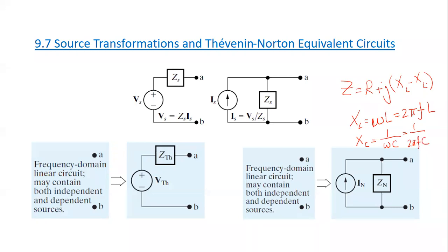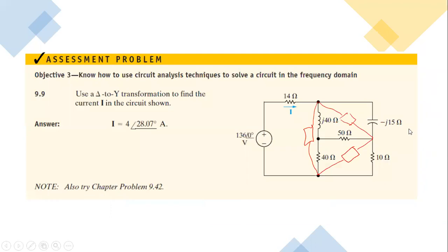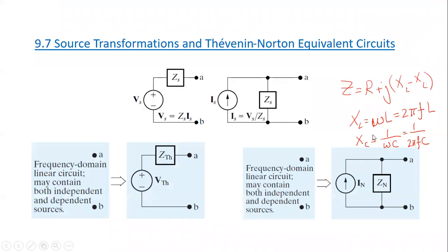So once you have the frequency given, once you have given the inductance in Henry or the capacitance in Farad, you can calculate the inductive reactance, you can calculate the capacitive reactance, and apply in these formulas. So for example, here we already have the capacitive reactance. We already have the inductive reactance here. So you don't need to apply these two formulas because you already have XL and XC. So you need to apply the impedance in this way.